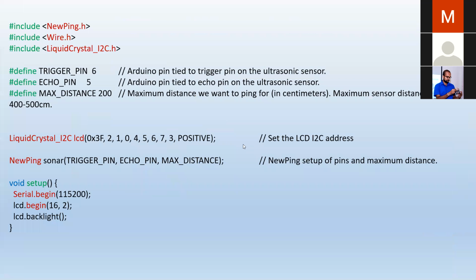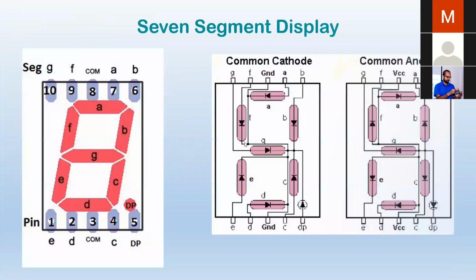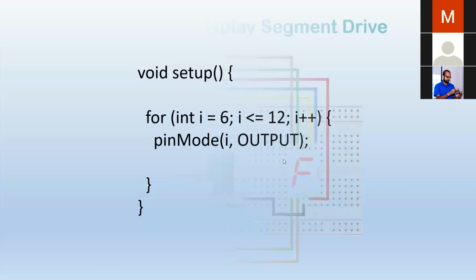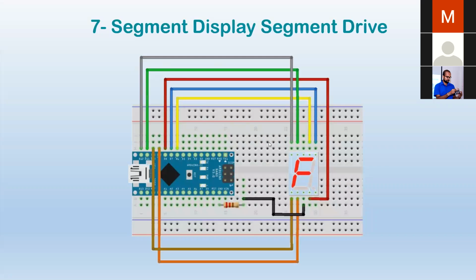So this is pretty much the syllabus we are going to do in the next few days. This is a 7 segment display, 7 segments, because we have 7 LEDs representing one number. This 8 digit can represent almost all the numbers we need, of course, from 0 to 9. If we have multiple of these displays, we can display any number we want, and there is a decimal point. We use a shift register to control this, but you can directly drive it, it's not a problem.